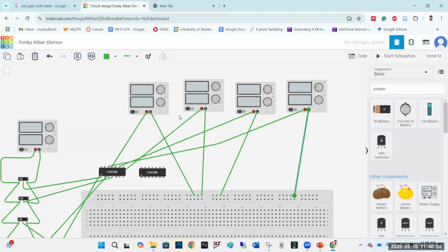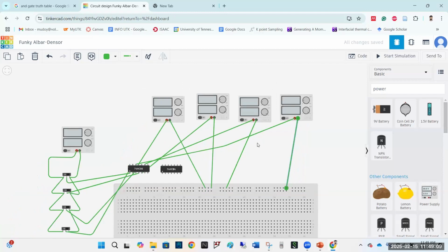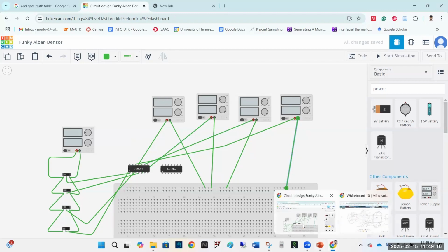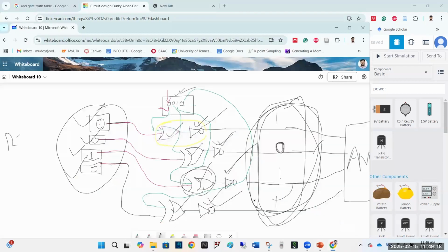So I have connected all the black terminals to this line of this breadboard. So I am treating this as my ground terminal or ground node. Okay. So I have connected the power supplies, the input. So we have connected up to this point. We have connected these things. Okay. So we have implemented all these things. Now we move to the next part.